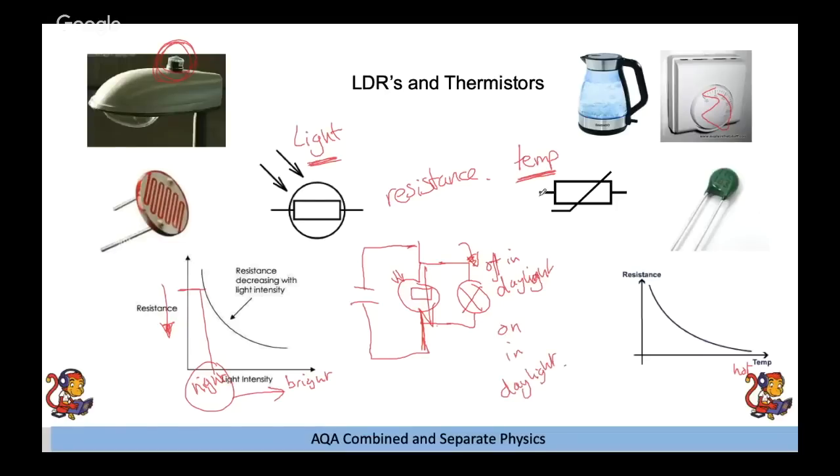Now for a thermistor, it really does depend whether you're going to turn on a cooling device or turn on a heater as to whether it wants to be in series or parallel.